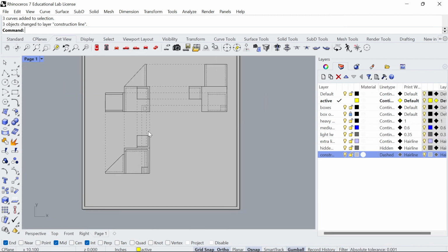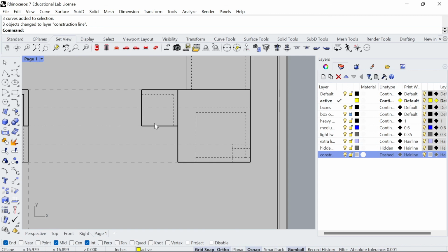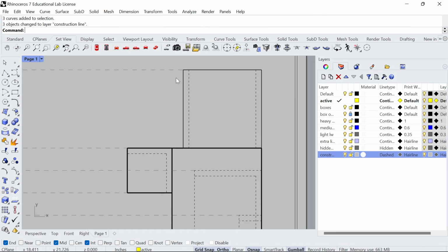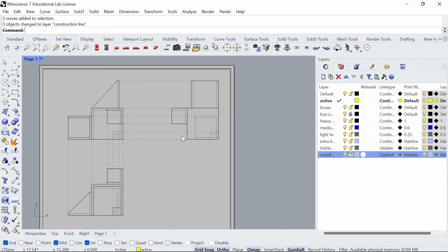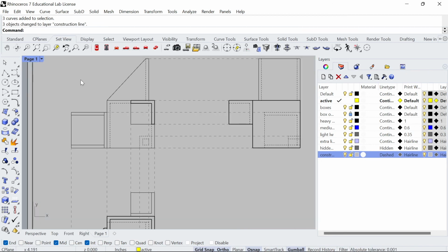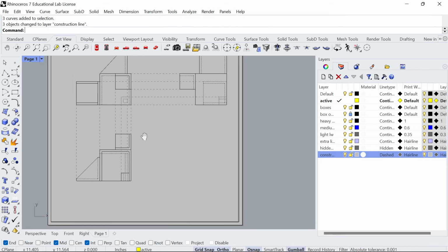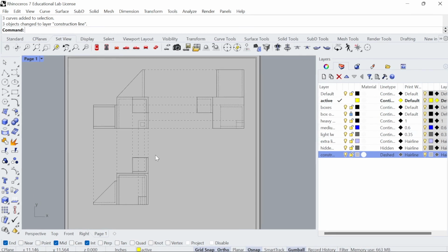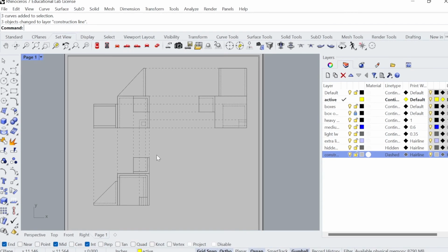So if we go back to the layout view, you'll see the line weight should be set properly. You'll see that these are kind of the heaviest line weights. This is the thinner one, or slightly thinner from the main facing ones. And those are your two side views and your top view. You typically want to label these things so it's not super confusing. But again, I'll go over annotation and page layout in a different tutorial with the addition of an auxiliary drawing.